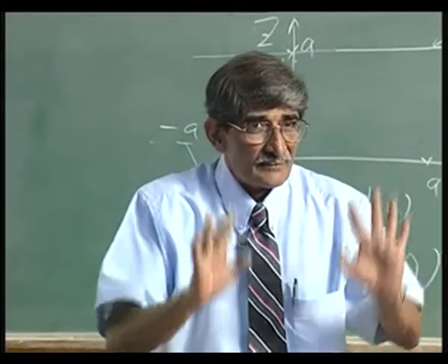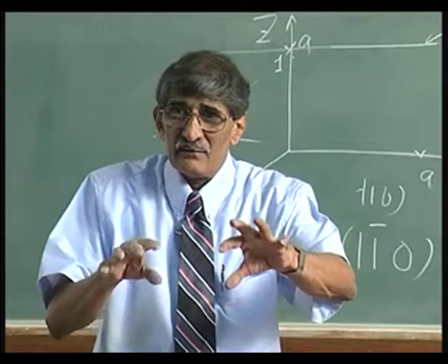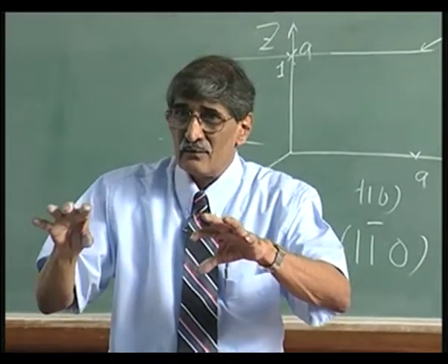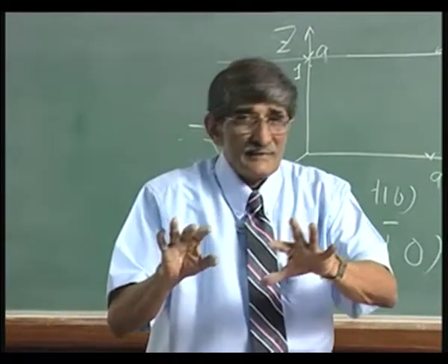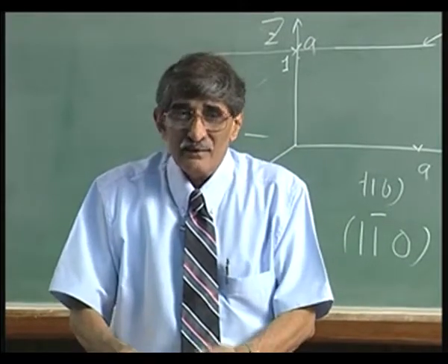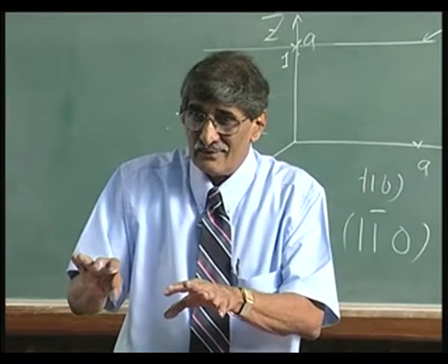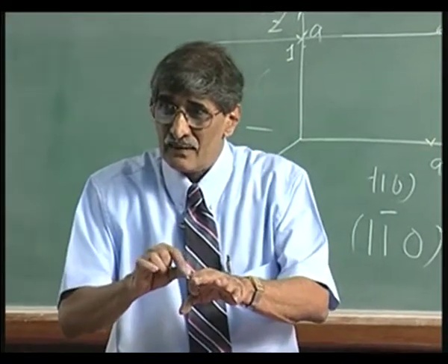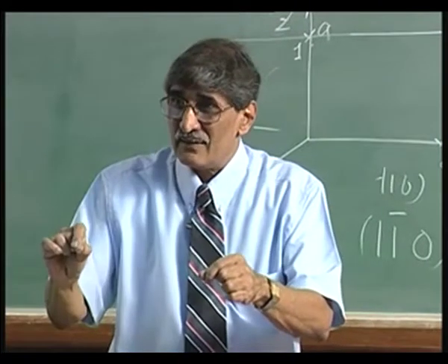This is a neutral plane, even if there is some charge. In fact, because gallium has got 3 and arsenic has got 5 electrons, there is some ionicity. The bonding is not perfectly neutral like in silicon. There is some shift of electrons towards arsenic actually. So, gallium will be slightly plus charged, in fact plus half, and arsenic will be minus half charge.